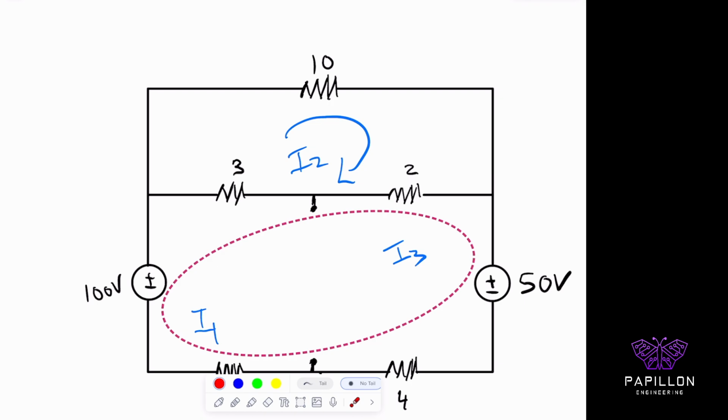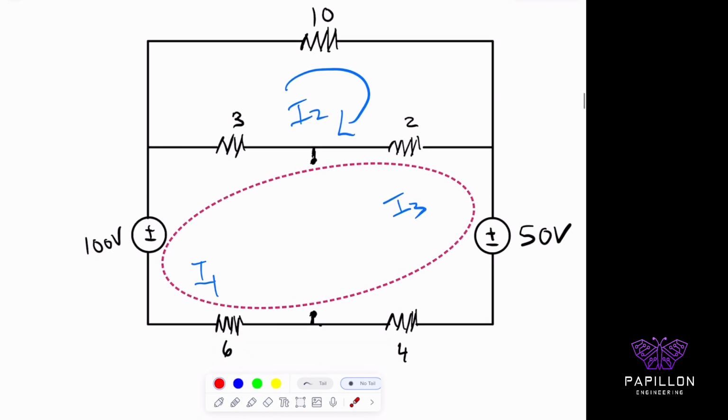That's the one unique piece of our circuit, which I've now combined. I removed the current source, and I'm writing an equation that solves KVL for one giant loop. That's what's so super or special about it, and it's given a name: our super mesh. Say it one more time: I remove the current source from my circuit, and when I do, I'm left with just two loops. One large one in red called a super mesh, and the other one just our traditional mesh current I2.